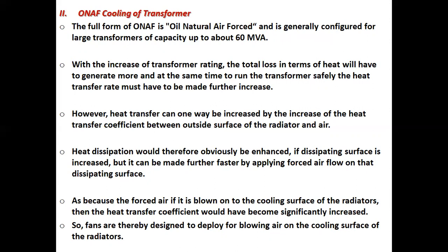However, heat transfer can be increased by increasing the heat transfer coefficient between the outside surface of the radiator and air. Heat dissipation would obviously be enhanced if the dissipating surface is increased, but it can be made even faster by applying forced air flow on that dissipating surface, because if forced air is blown onto the cooling surface of the radiators, the heat transfer coefficient becomes significantly increased. So, fans are designed to blow air on the cooling surface of the radiators.